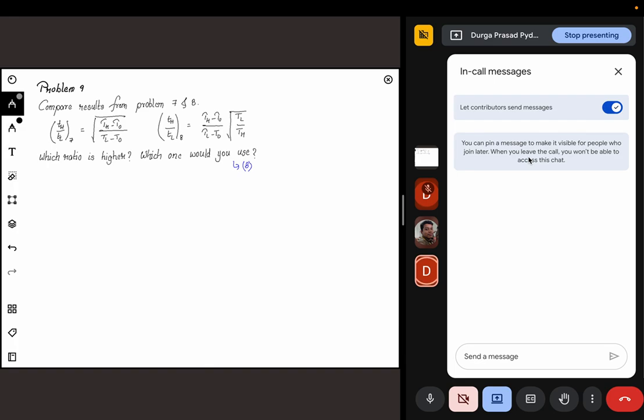So what we are trying to do from the beginning is, I have a certain amount of insulation and I'm trying to distribute it to two surfaces. The question is, what is the ratio in which I have to distribute the insulation across two surfaces, one hotter and one less hot. Now, using one way, I found this one, assuming that both are equal weightage. Using a different way, I found this ratio. The question now is, which thickness ratio is higher? So basically what this asks is, in which of these two cases will the hotter furnace get a thicker insulation?